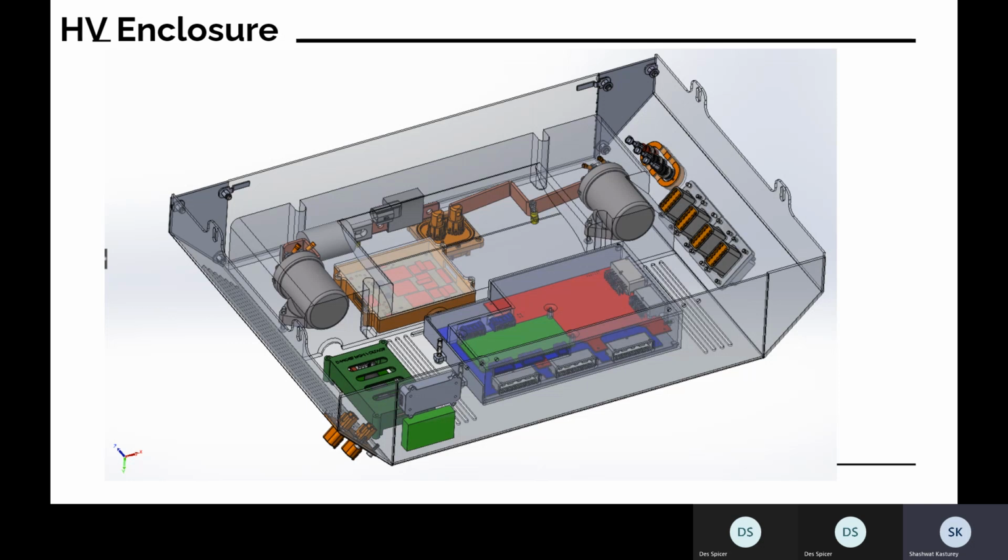Most error handling works this way: the VCU will command the relays to open. The relays are the accumulator isolation relays. So in most events where something goes wrong, those relays open, and power doesn't flow through them.